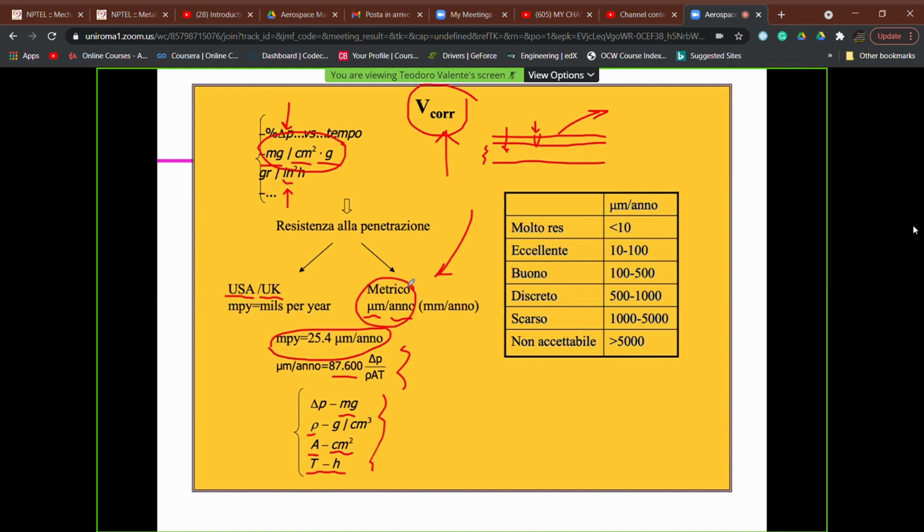For a very simple consideration, because if you, for example, have in front of you a system which is subjected to a load, let's make the very simple case of a system subjected to a tensile load, so we have a positive stress, we are able to calculate during time how much force this system is able to sustain, which will be a reduced force due to the reduction of thickness, which implies a reduction of the resistance area of our component.